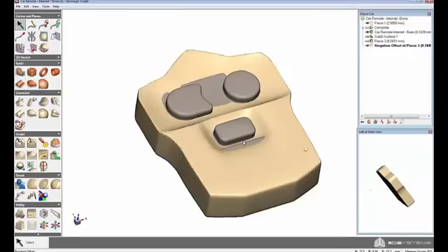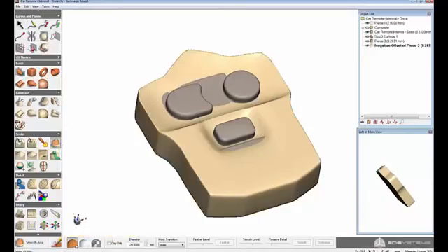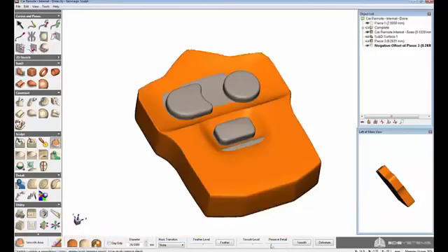I had that ogre face. That ogre face has lots of crevices, lots of interfering geometry. But once you're in voxels, you're able to go ahead and do things like offsets, either in or out, without a problem, just because we're using volumetric technology here. So I'm going to smooth that out so the insides are nice and clean when we do cut that out.